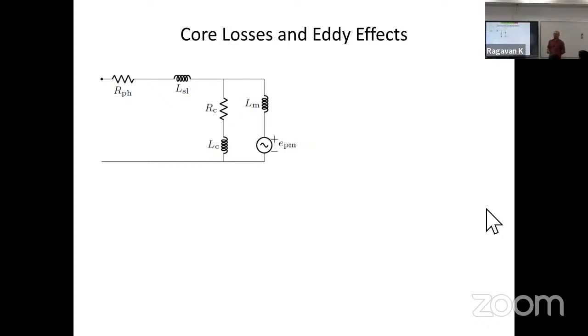You expect that the rate of change of back EMF will be constant. I'm assuming everybody knows that back EMF is given by some back EMF constant K_B times omega_E, right? So if I keep increasing the rotational speed, is K_B constant?